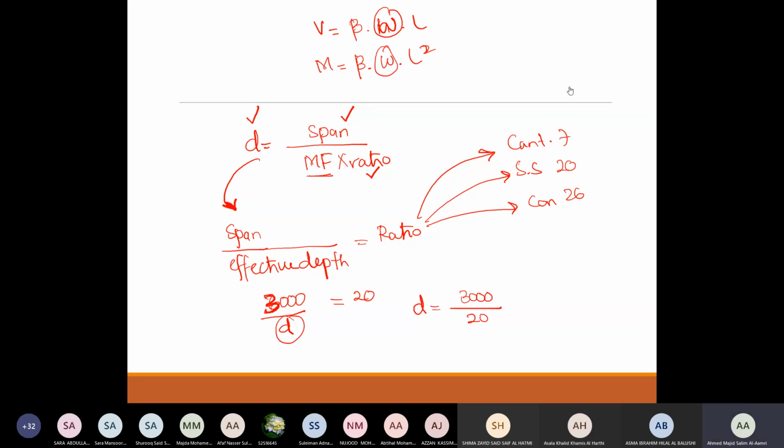Whatever you have taken in design one, you have not seen a slab which is doubly reinforced, but you have seen a beam which is doubly reinforced. You should have asked yourself why the beam got doubly reinforcement but we didn't get it in the slab. Why do we have links, shear reinforcement, in the beams?